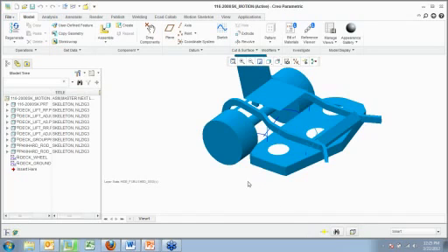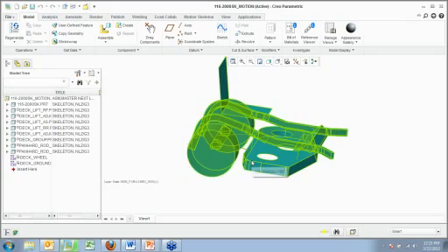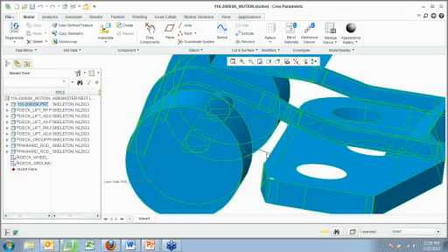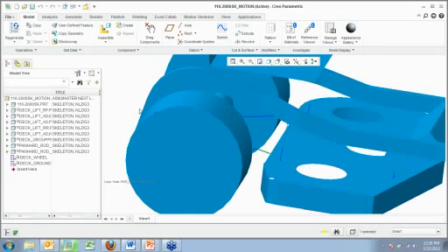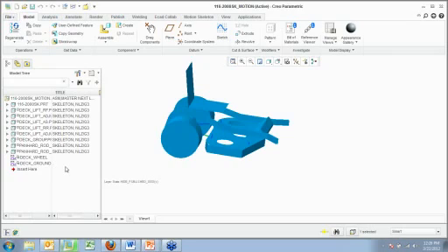So I open my skeleton, and I'm going to click on View 1 here, and I'm going to go in and maybe edit some of the dimensions. I can pick a component here, pick a specific line, and actually edit the properties of it, and it'll show you all the details. I'm sorry, I'm in the wrong skeleton view to show you that. I'm still in the motion skeleton view. But my parts are all based off of this. They're all constrained to this. As I update this, it will update the parts that I'm basing this off of as well.